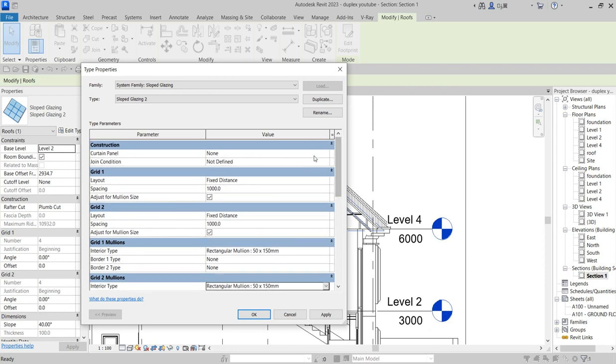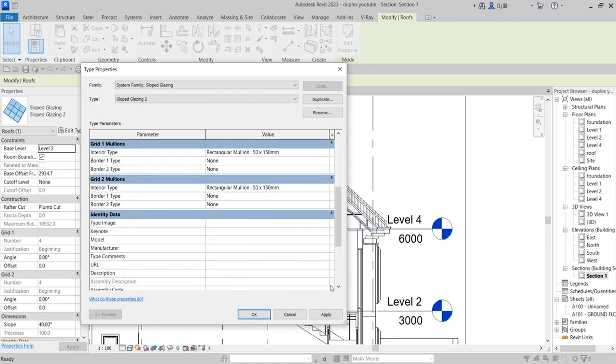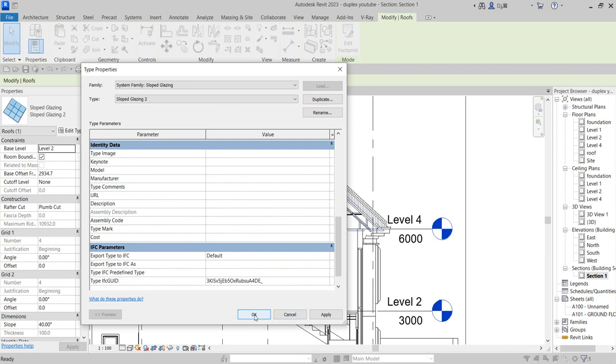So here on the curtain wall, you click on this and say empty panel system. So define junction, define none, you can do continuous level 1 or something like that. So these are the things that will define your key moments. So apply this, I say okay, look at the graphics, it's going to transform to something bigger.